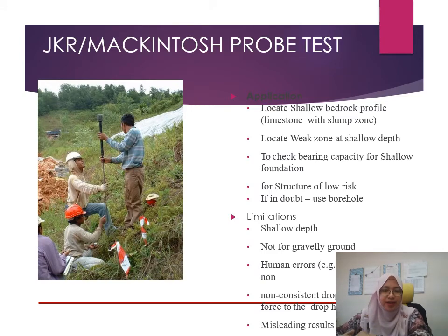As you can see here, this is a group of people conducting a probe test. Here is the hammer, and below the hammer is the steel rod. The steel rod is extendable, and we can join one steel rod to another with a connector, and it can go up to 15 meters in length. The application of the probe test is that we can locate the shallow bedrock profile within 15 meters.